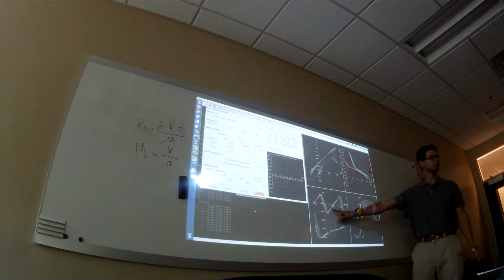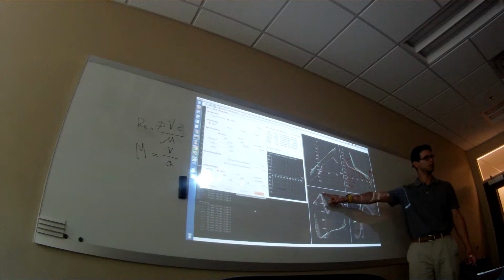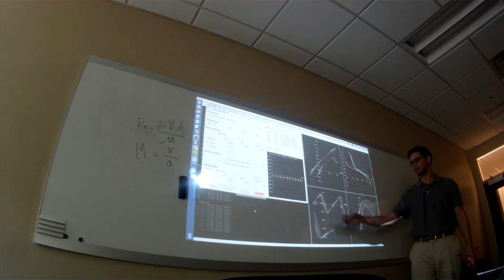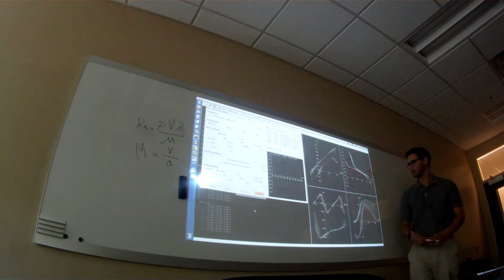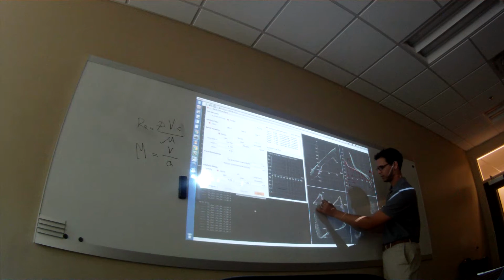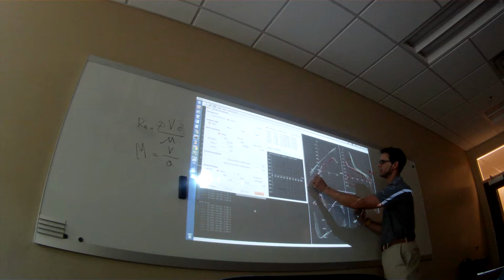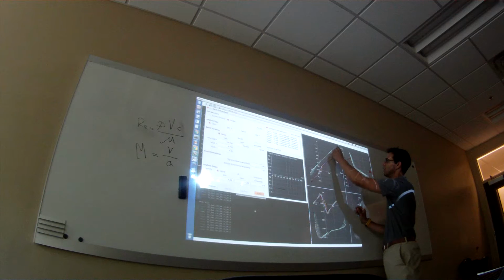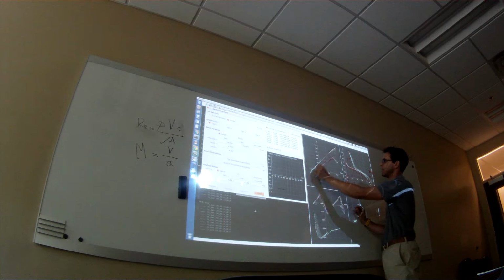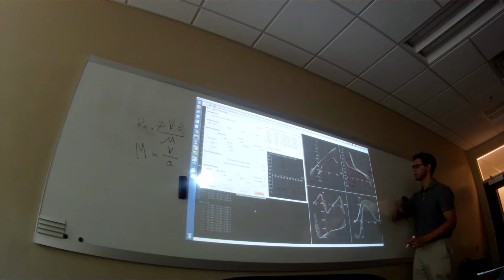That's what this is here. This is the pitch moment as a function of angle of attack, and it's all over the place. If you are very, very close, it's linear. Everything is linear close to the axis. Here's where you stall. This is fairly linear. This is a pressure distribution, so that's not.